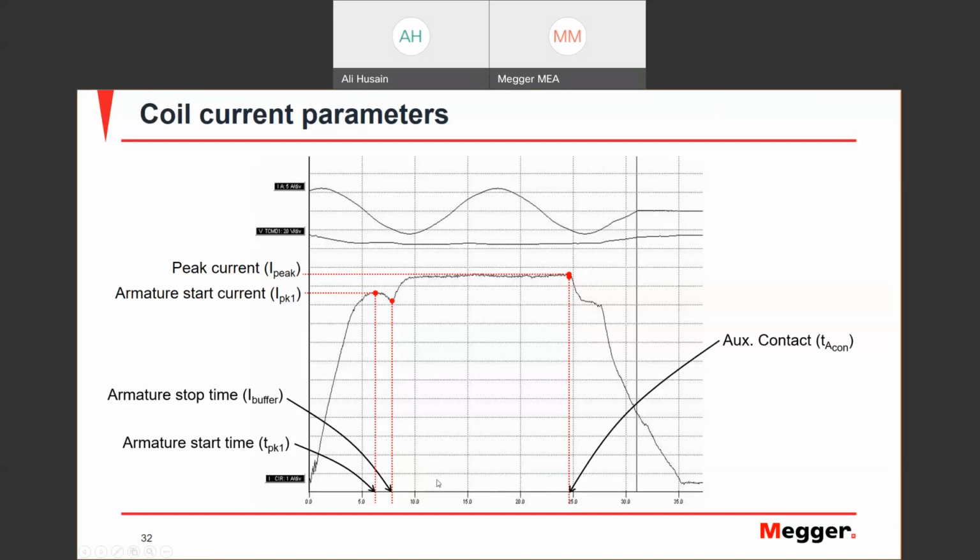If this time is longer than the previous or reference time that you get from the factory, then your mechanism has a bad lubrication, maybe with a little bit of rust or dust built in inside, that maybe needs better insulation of the mechanism.